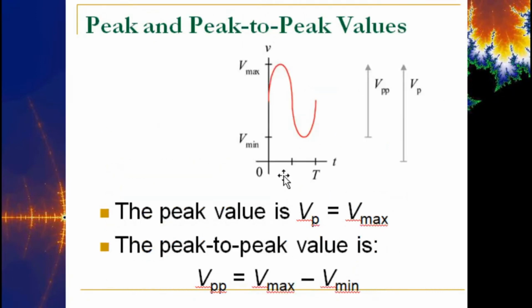So in this particular case, that's true. However, in this one, there's a DC offset that it's riding on. You can see that, right? So I don't know how many volts that is up here, but there's an AC and a DC signal together. And when you have that, the AC signal rides on whatever that voltage is. And so you could have a positive DC offset. You could also have a negative DC offset. Wherever that offset is, the whole signal rides on that voltage. If there is no DC signal, then it rides over 0. Okay? And so what number do you input for sin?